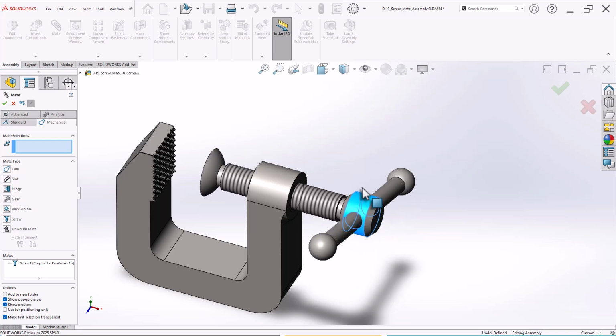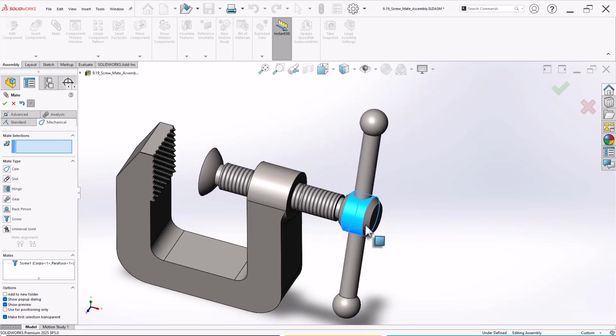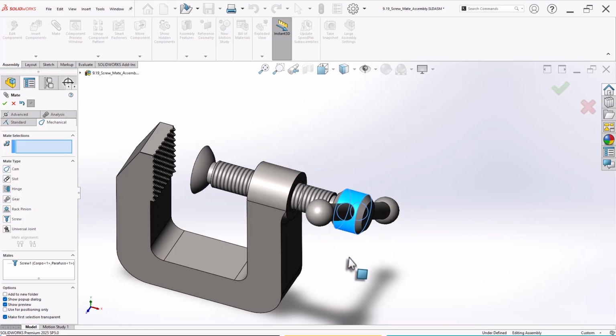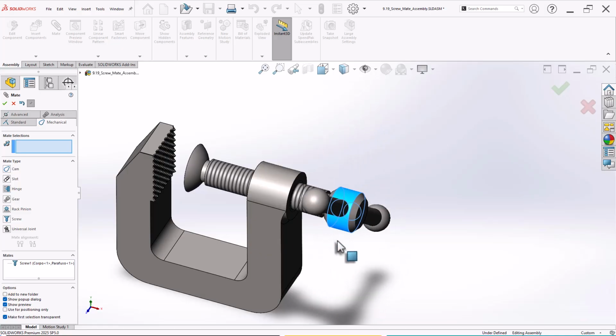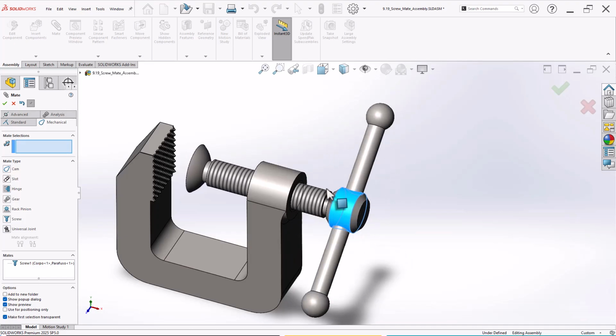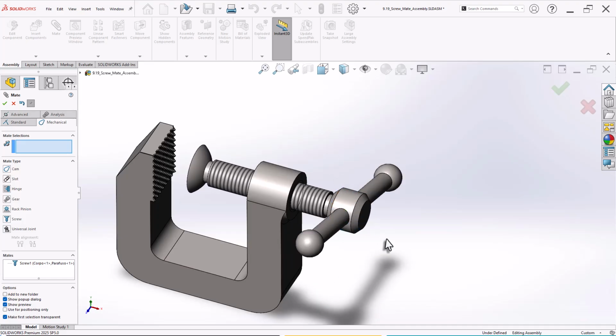So if I give more distance, 2.5 or 5 or even more, then with the minimum rotation the screw will travel faster. So it's a relation between the pitch and rotation. So using this kind of screw relation, you can create a screw pair motion.